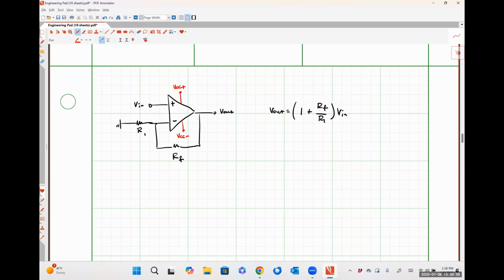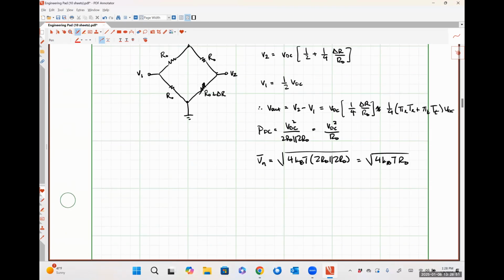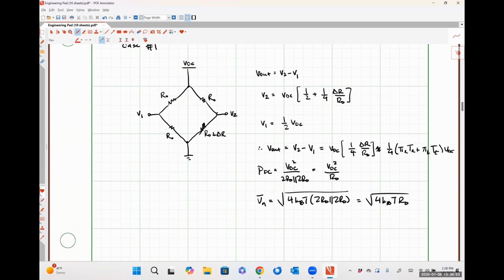So we potentially might not be able to see what that change due to piezoresistance is, because we're amplifying the DC portion of that input signal as well. This guy here doesn't have a DC portion of the input signal, and while it is twice as noisy and twice as power consuming, we don't have that problem. All we're amplifying is the output that is dependent on the piezoresistance. Okay.